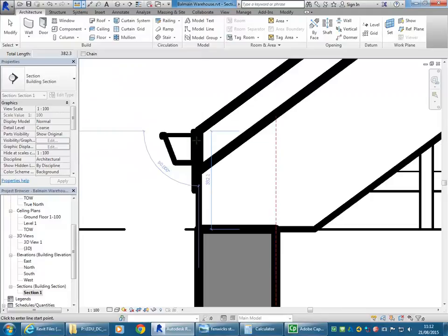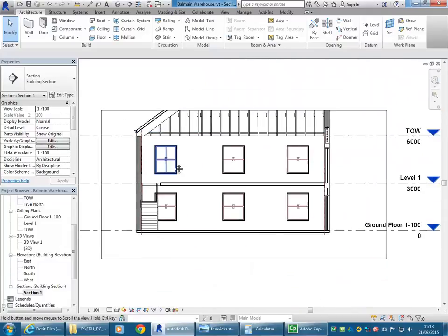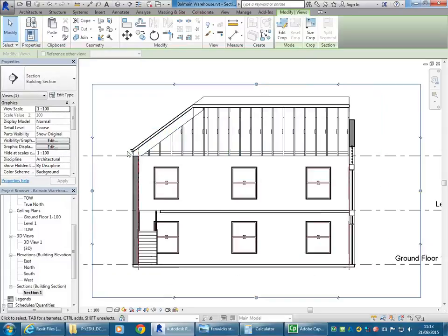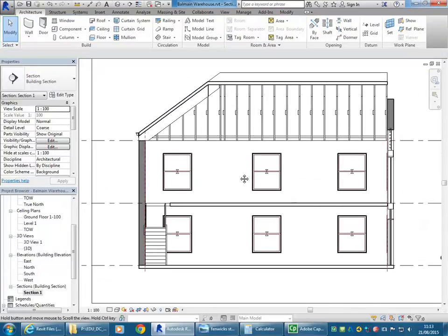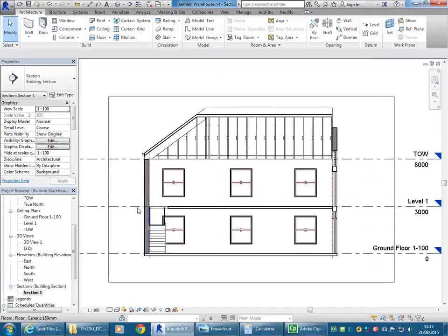So it's not essential that you do that, but it's not a bad thing to try. So yeah, something like that. You might have clicked on a different point, but yeah, it's about that. So I'm going to make it a bit bigger. So 400 is the size I want for the fascia. And it's good though to get used to switching to views like your section so that you can see things on the interior or that are cut through in your section, like the other bits of the structure there.